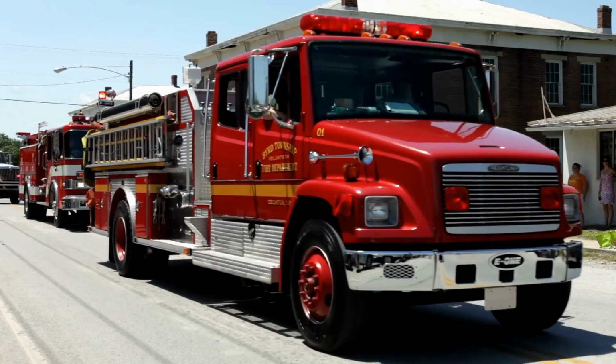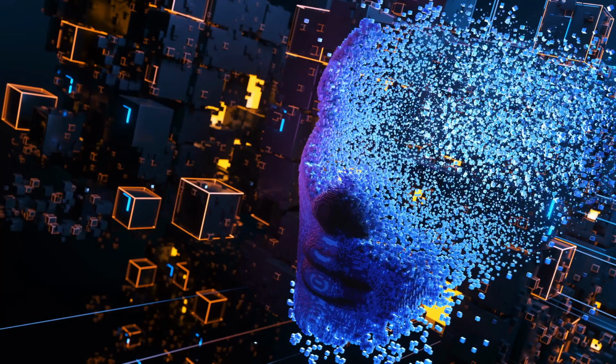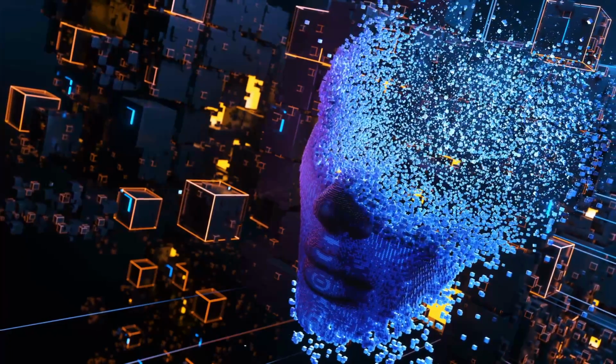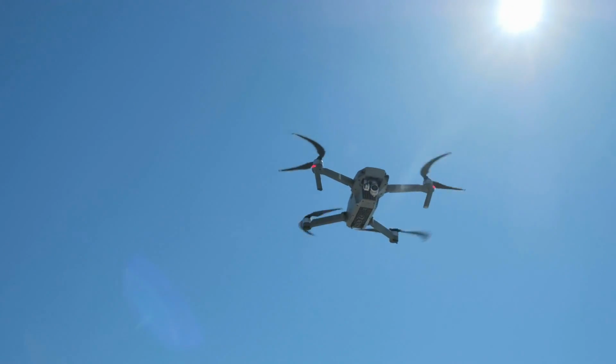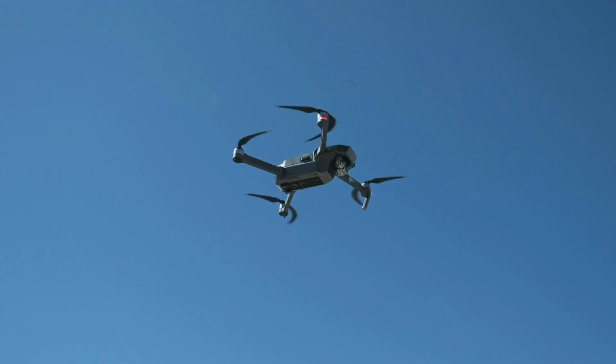Cameras are really good at getting 2D information. They're not really good at getting three-dimensional information: the size, the shape, the depth. You may do a little better using stereo vision, using the epipolar plane when you have multiple cameras at different angles, and then you can get more depth. We'll often get better information with LiDAR if you have the compute to handle it. 3D deep learning has definitely been growing: recognizing things within a scene, filtering LiDAR information, and using trees to more optimally process it. There are drone companies that use audio information to tell where something is. If you're using audio, you want to do more signal-based processing.